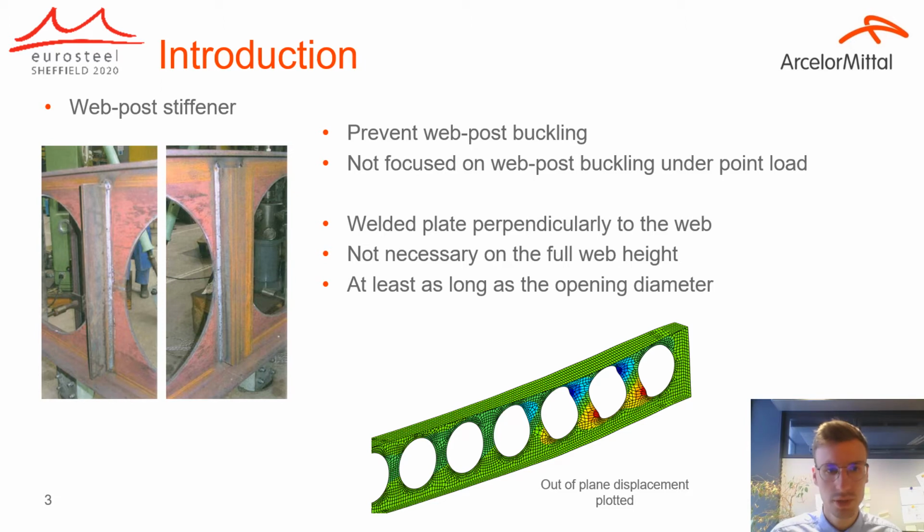A couple of assumptions here. The stiffener doesn't have to be the same height as the web and doesn't have to be welded to the flanges, but as you can see here on the deformed shape, it should be at least as high as the opening diameter to really prevent the buckling.